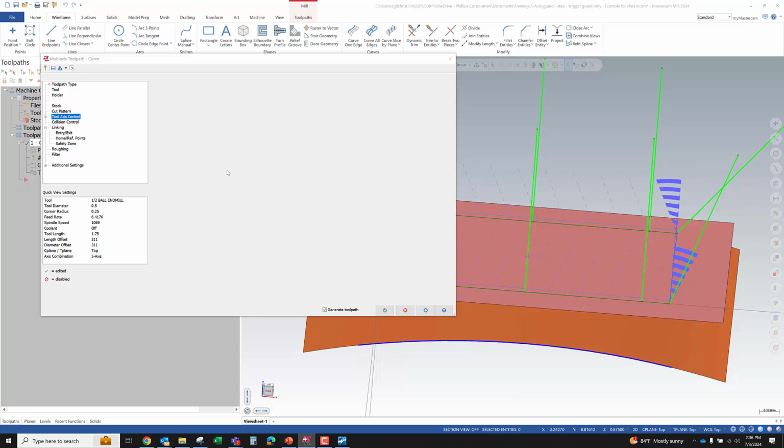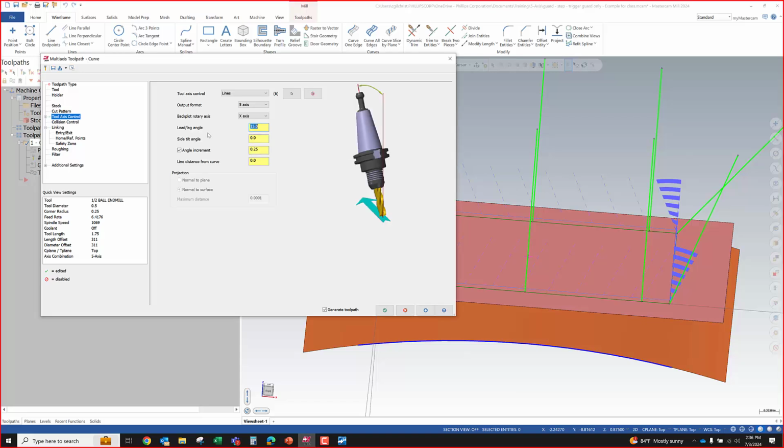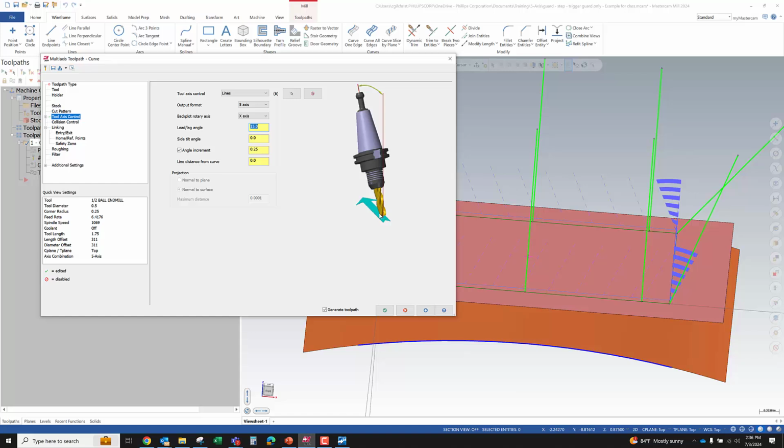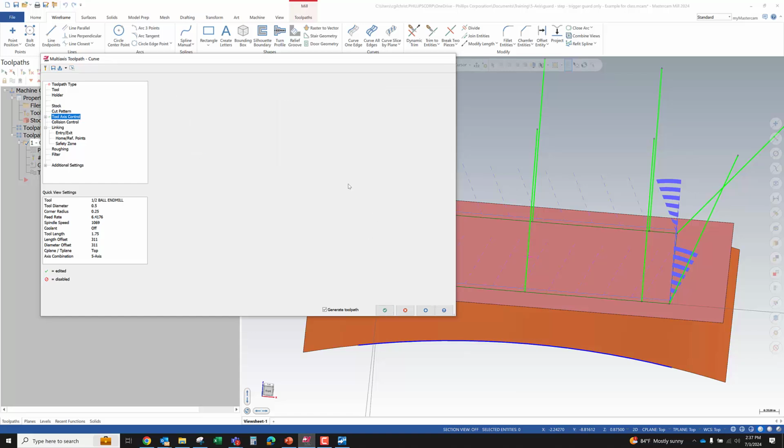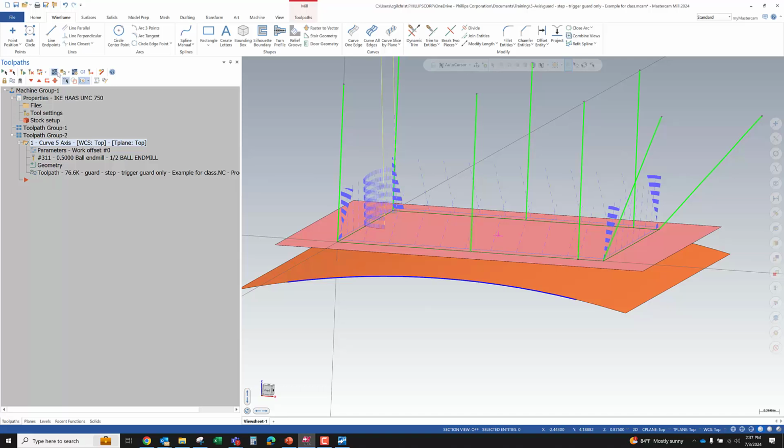Sometimes tool axis control can make all the difference to get the contact point of the tool on the tip where you've actually got some flute, instead of on the very center, where even with a center cutting tool your effective RPM approaches 0. Right? So we've got a 5-axis tool path and 5-axis machine capability. Let's rotate the tool so that the contact point on the ball is much more where we actually have flute that's capable of making the cut.